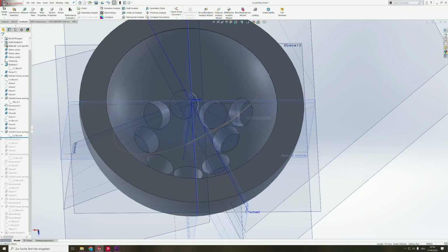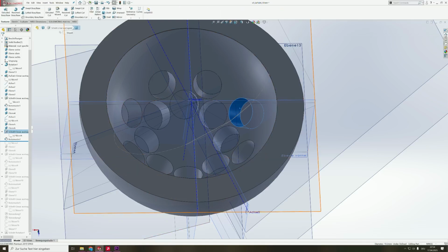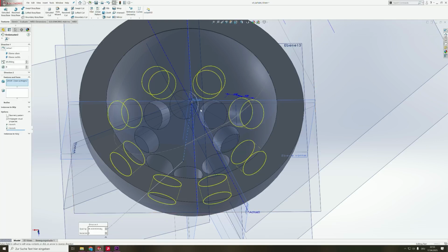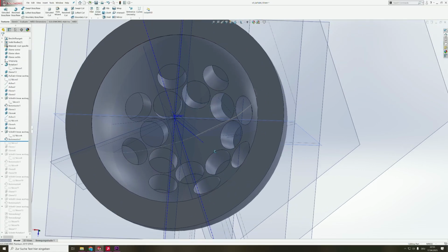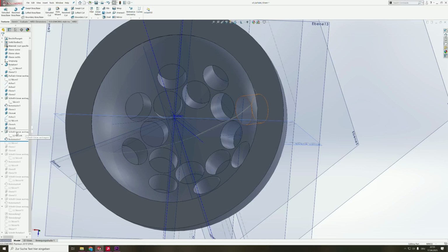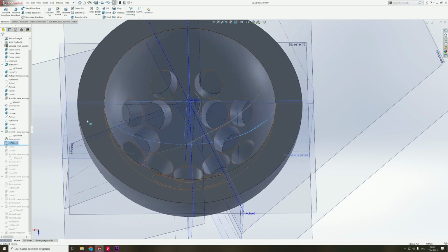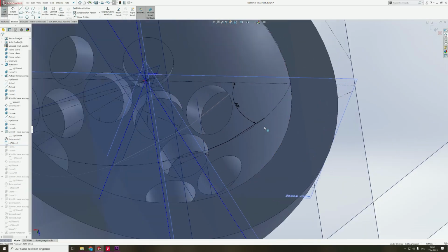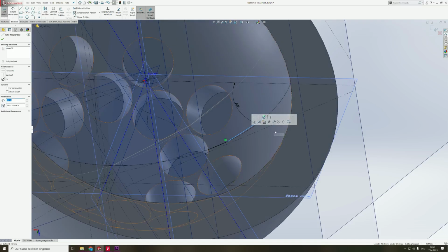Then let's go back to where we were with, again, this hole that I made. I also used the circle pattern feature. You can find it here, circular pattern. Again, we use this one hole, repeat it 8 times, and we get 8 holes out of here. And then you will see the steps for the other holes will just repeat. We make another sketch up here. Let me show you. We assume where our hole will be, draw a line of 10 millimeters, or just up here.